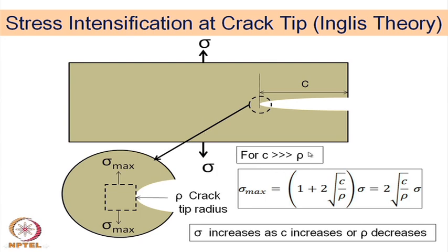So, that is one of the major reasons why once a crack is generated and a sharper crack is formed in a brittle solid, it propagates almost instantaneously, and there is hardly any plastic deformation which is led by this crack propagation. This is unlike dislocation, where dislocation does not lead to crack immediately. When a large number of dislocations pile up together and the stress at that particular point increases, then only the crack gets generated. So, before that, only a few dislocations or a single dislocation does not lead to a crack.